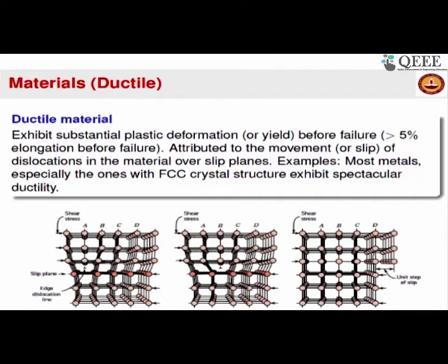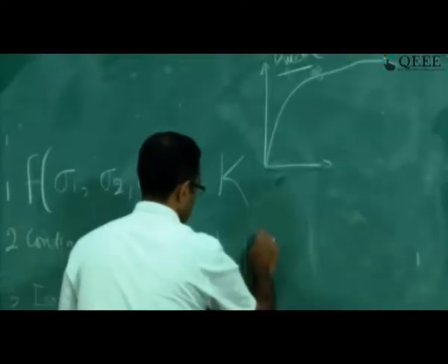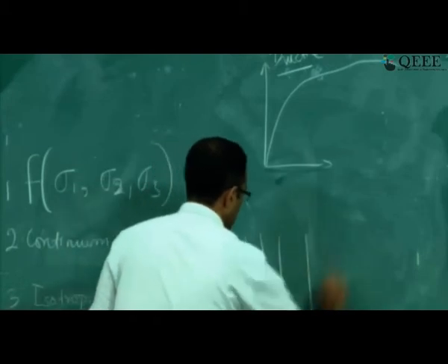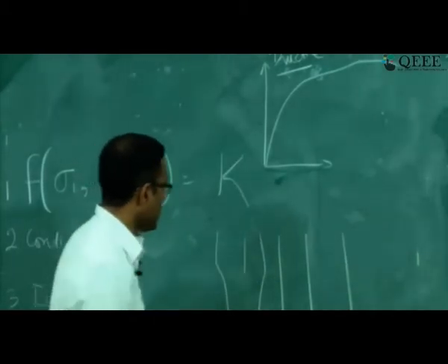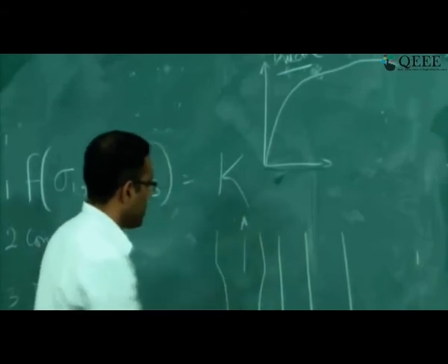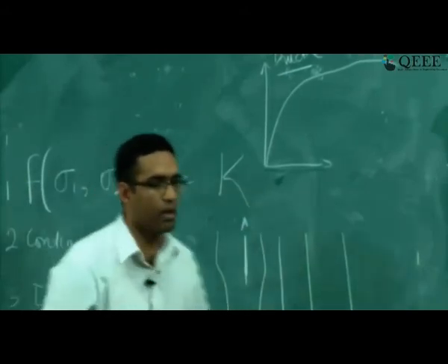Allowing the dislocation to slip forms a very important criterion to enable yield. If we all agree that yielding is actually failure, then for the material to fail, you need to make the dislocation move. Okay. Now as you can see, suppose this dislocation, I am just representing the atoms as lines. This is that extra plane of atoms A that is there in slide number 16.